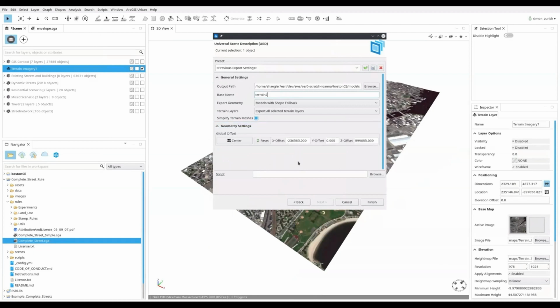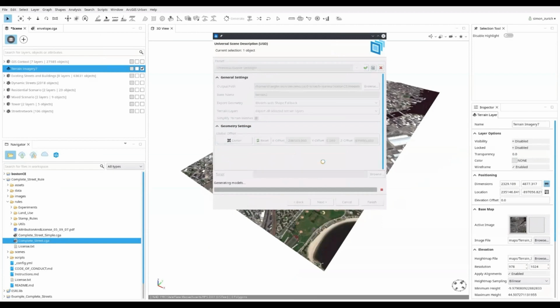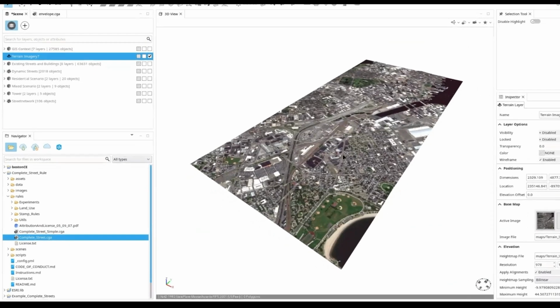The most important option for georeferenced scenes is the global offset, to de-georeference them. Here we will center the exported geometry around the origin to prevent precision issues in Houdini later on. It is useful to round the offset to some memorable values, so we will be able to reuse them later in case you want to do more exports, and so that everything aligns.